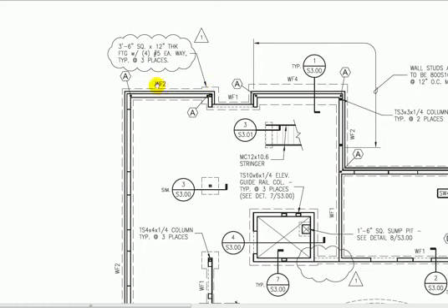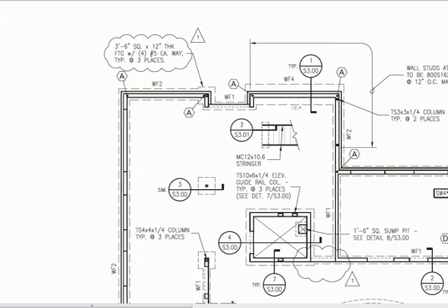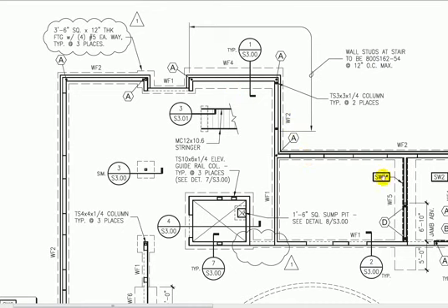What else do I see here? I see WF2. Well, WF I'm thinking maybe is wall footing number 2. And so whenever we see a tag like this, usually indicates that the information is found in a schedule somewhere. So I'll have to go to a schedule to find out what WF2 means. Over here I have SW4 and it's pointing to the wall.